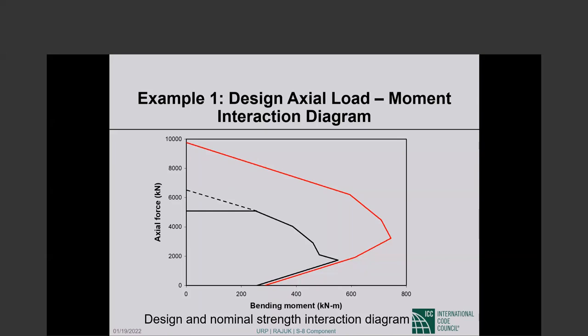The second thing, top bar versus other than top bar. Top bar versus other than top bar is for horizontal members, not for vertical members. People have used it in walls and things. I personally do not believe that it is meant to apply to vertical bars in walls or columns. So don't worry about top bar effect when you are splicing column bars. That simply does not apply. Okay, next.